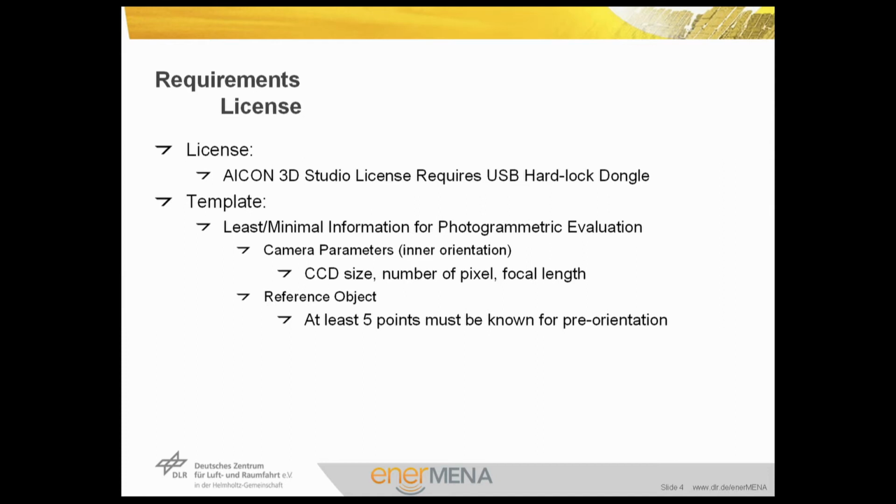Then, the reference object is also part of the template. The reference object are the 3D coordinates of the 5 coded targets on the reference cross. These coordinates must be known with high accuracy because they are needed for the pre-orientation during the evaluation procedure.